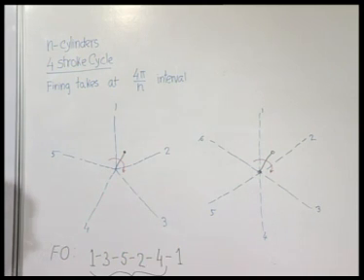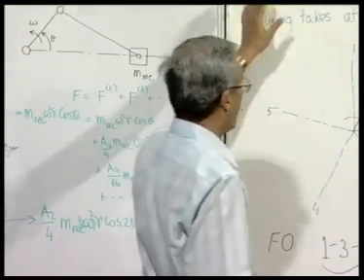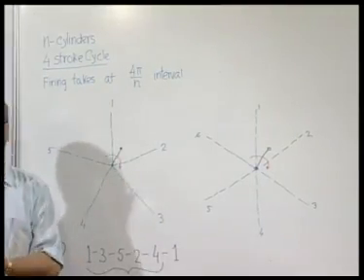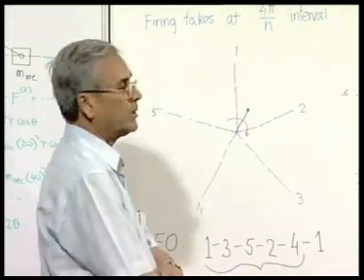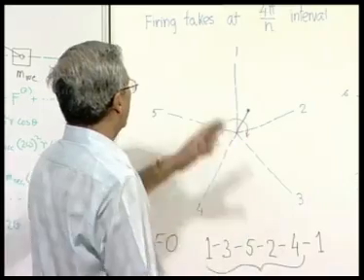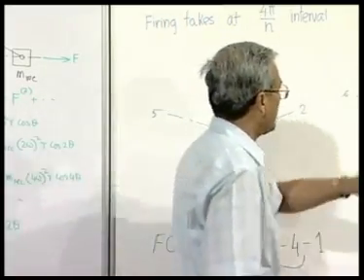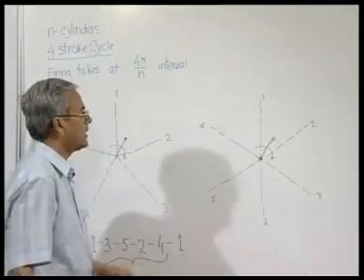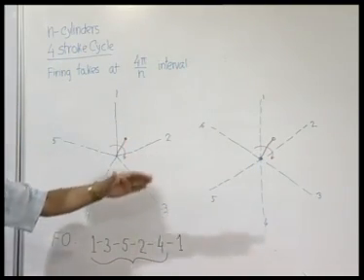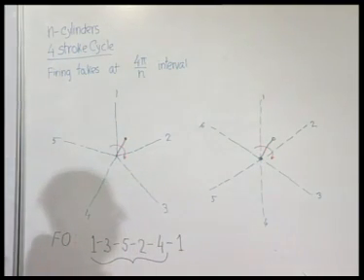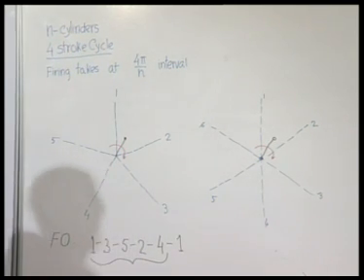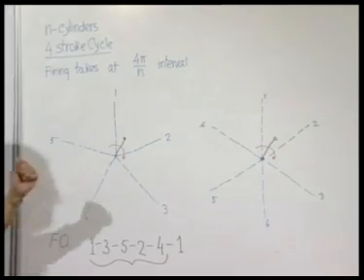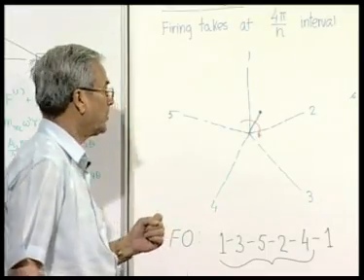So, therefore, one thing is very clear, that if we use a 4 stroke cycle engine, the number of cylinders should be odd. If it is odd, then there will be no problem in getting all the cylinders fired. So, with an even number of cylinders, alternate cylinders do not get a chance to be fired if we want to maintain equal angle between the firings to maintain the uniformity. So, therefore, in general we will find in radial engines we have an odd number of cylinders. That is something which you have to keep in mind.